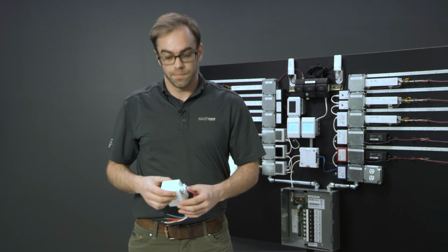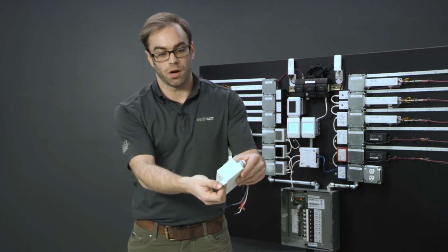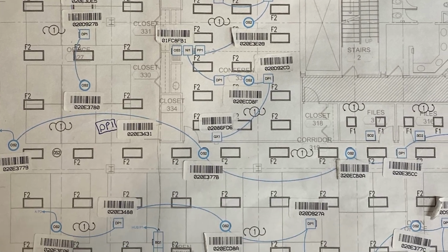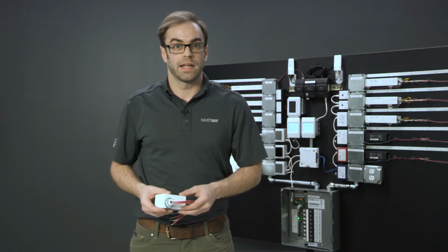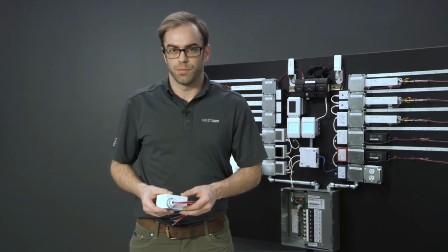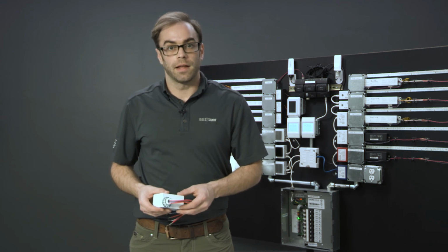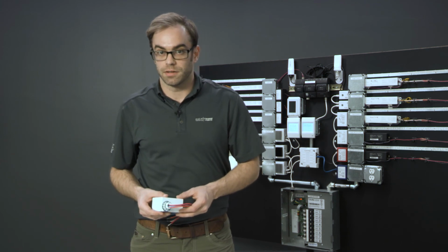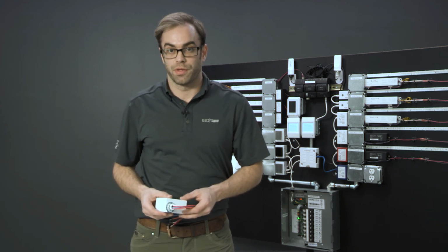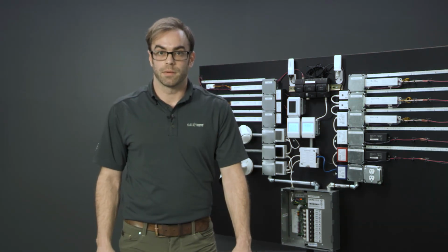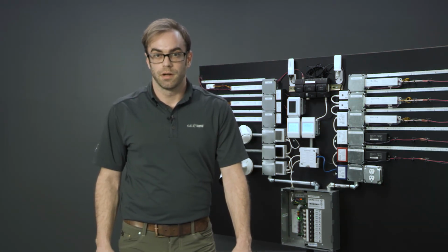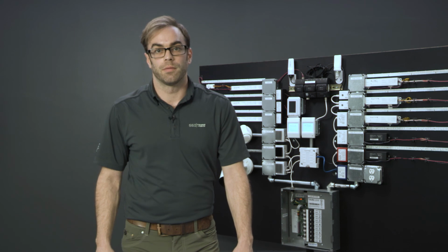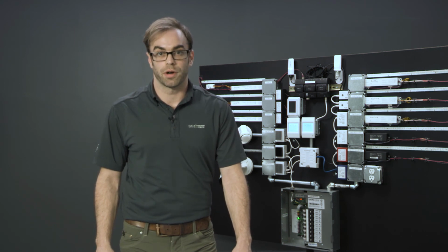When installing these devices, it's very important to grab one of the loose serial stickers off the device and place it on a reflected ceiling plan where the device is installed. This will be vital for your field service engineer to accurately and efficiently start up a site and troubleshoot more effectively if necessary. nLight-enabled fixtures will have the sticker directly on the fixture, and if the nLight-enabled fixture has an embedded sensor, there will be 2 stickers. Grab both. If you have properly terminated Cat5 cable and have followed the daisy chain topology, your nLight system should just work out of the box. Your field service engineer will be able to finesse the lighting controls operations through programming.